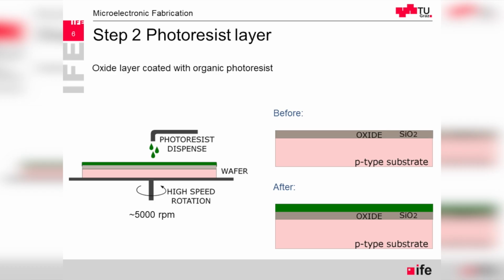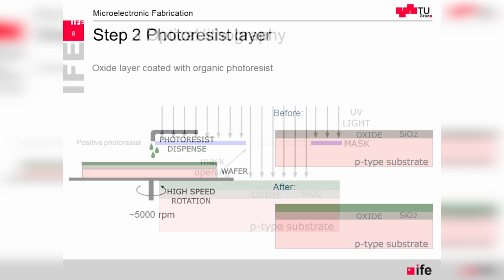So we have started the processing by simply applying this oxide. Then there is the photoresist dispense, and this is going to be used for photolithography. So what we would like to do is create an opening to make our N-well implant. And inside this N-well, the P-type transistor is going to sit.